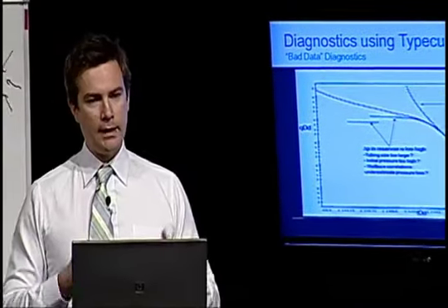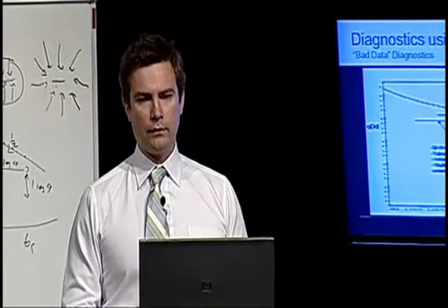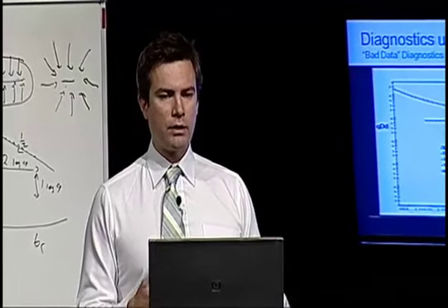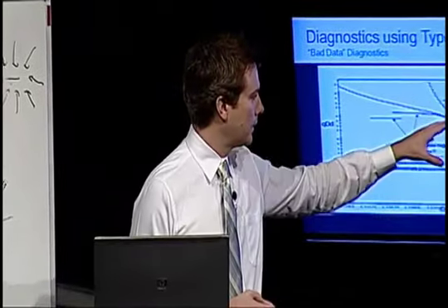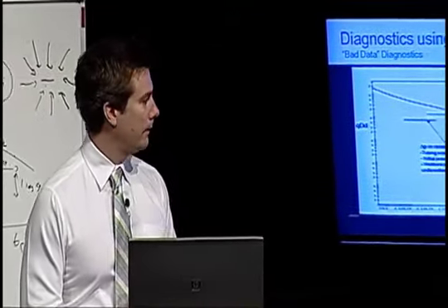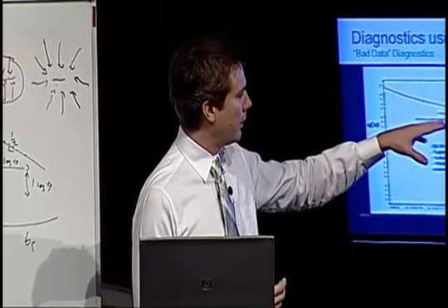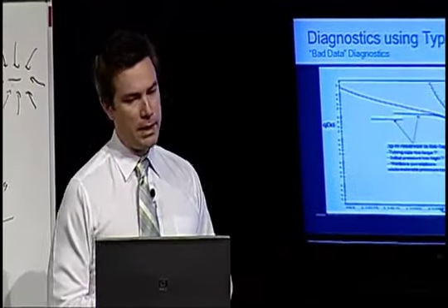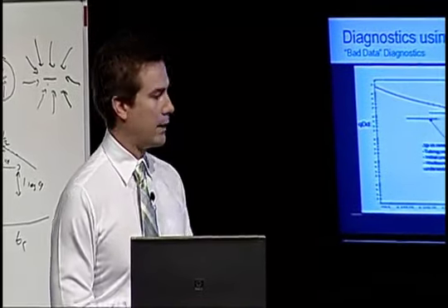The problem is the data comes to us after it's been measured on the surface. So when we reconstruct these pressure loss systems, we may overestimate the pressure loss because we think that there's all these liquids downhole. So these are the sorts of things that can happen. So we just need to be aware of potential problems that can be caused by bad data. And that basically wraps up the section on diagnostics.